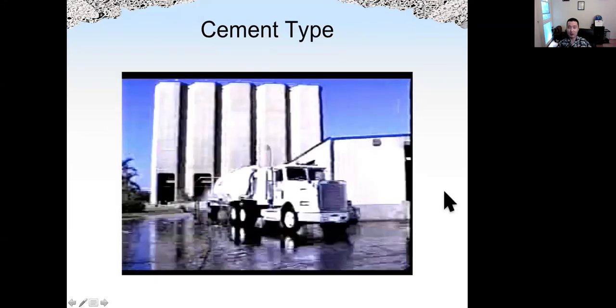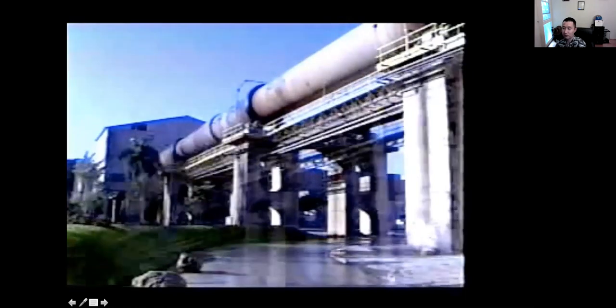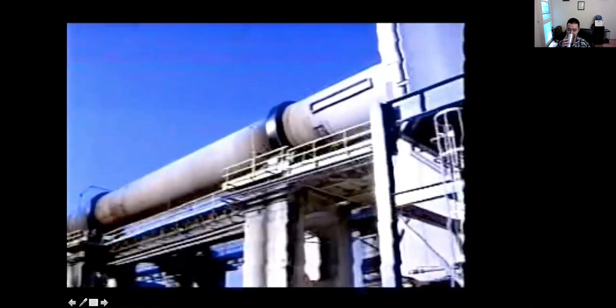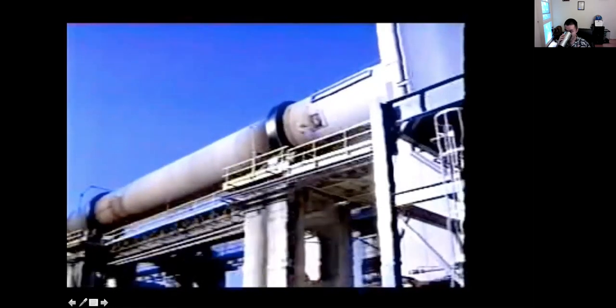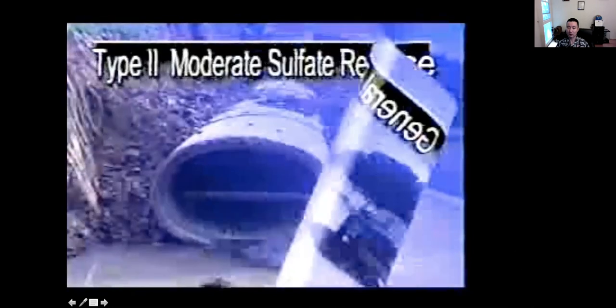There are five major types of cement. As we can see from this video, what they are and where they are used in different types of applications. There are 5 types of Portland cement produced in mills like you see here. These different types can be used to suit various design and construction needs. Almost all uses of concrete can be made with type 1, a general all-purpose cement suitable for buildings, bridges, floors, pavements, and precast structures. But some concrete structures require special needs.